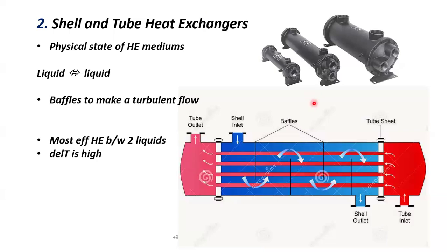Due to long-term use of these shells and tubes, the fluids may have properties such as corrosion, and due to the abrasion of the flow, some dust or rust particles are carried along in the fluids. At the same time, these fluids are treated with some kind of chemicals. Due to those chemicals, a small scaling is formed inside the tubes and shells. That process is called the descaling process.